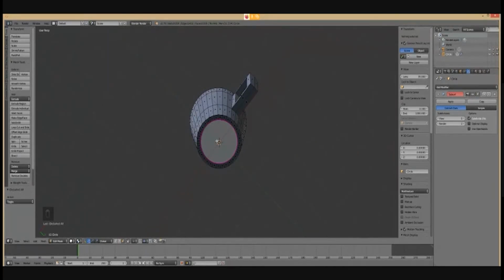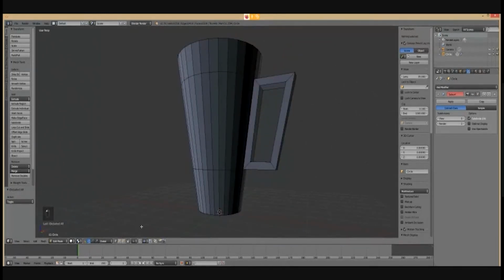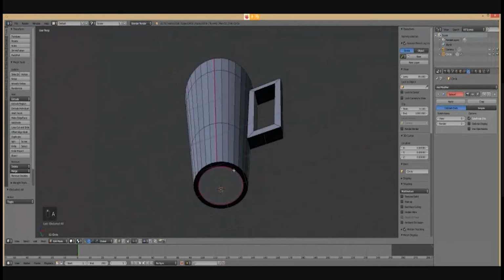So our bottom circle was getting deformed. You can imagine it sort of getting pulled, like a bed sheet trying to get pulled. When we apply mean crease, the boundary of the circle that I have selected over here maintains the sharpness, right? So I'll give you another example. I will apply mean crease, for example, to one of the sides, right? So let me select the edge. Let me go to mean crease and keep it at 1, right? So right now I've applied mean crease to two things. One is the bottom and one is this line.